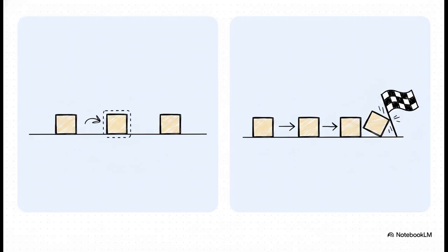But to really engineer schedule flexibility, you have to deeply understand the difference between free float and total float. Free float is basically your local maneuvering room. It protects the start of your next specific activity, meaning you can afford a slight delay without messing up the very next crew in line.